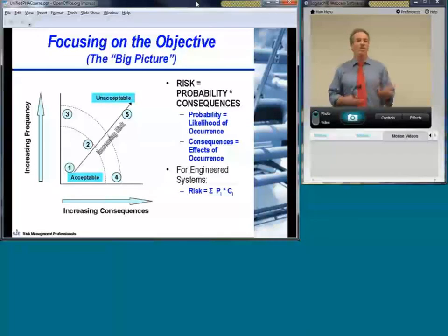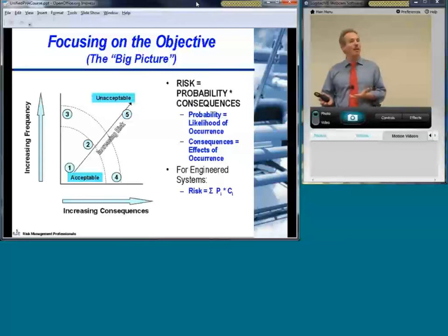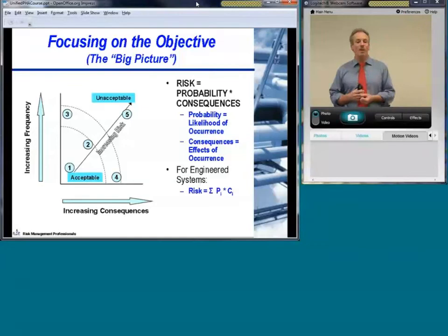So what you're using the HAZOP study for is to look at the likelihood of the event, the consequences of the event, as a measure of importance. Things that are higher on the risk curve, as you look at the line that's going through the center of your screen on the graph, risk is increasing. So you're really looking for those things that have enough consequences and enough likelihood to make them important.